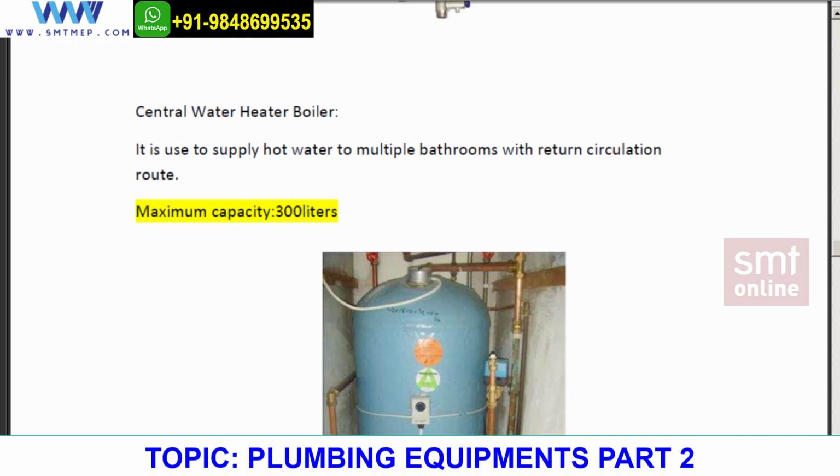We'll be discussing this and sizing these different pipes when we deal with the project, because what we are about to deal with in the project further is a central heating system. If it was a geyser unit, it would not make sense, because it's just cold water in and hot water out. That's it. It's very simple. But with a central system you need to think. That is the main catch. So we'll be seeing cold water, hot water supply and hot water return.